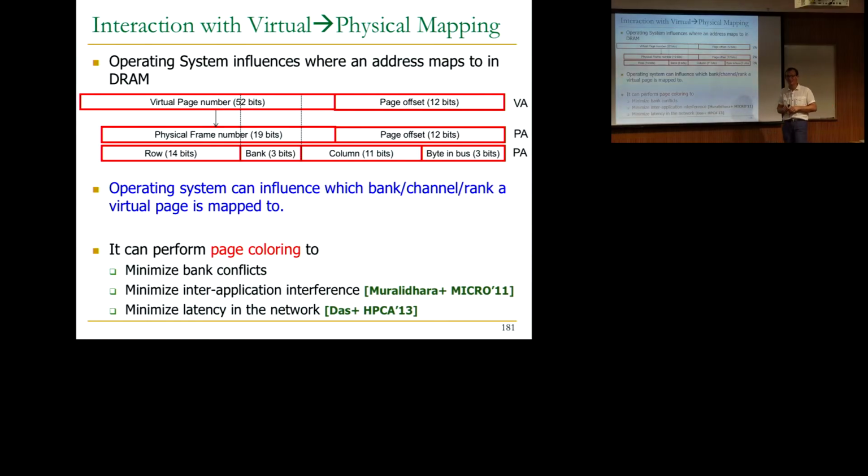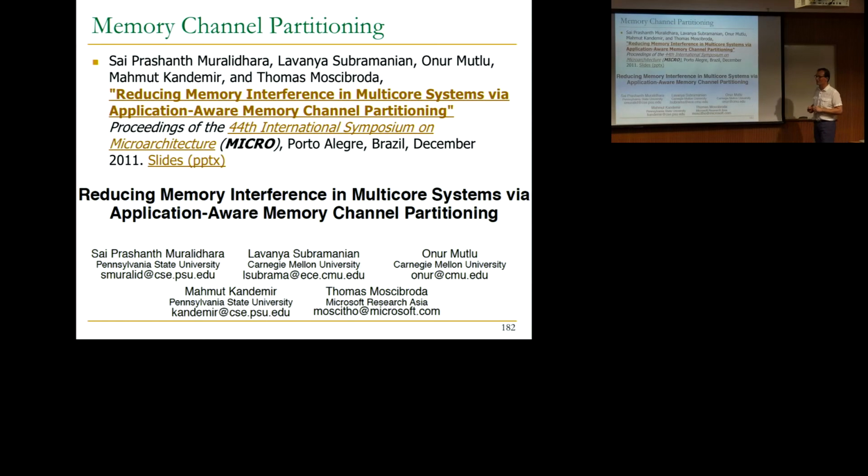That's limiting progress. Yeah, because I asked that because today you can buy some brand of a DIMM and you can just plug and play it, and that's all. You don't need to configure anything to install a DRAM. Well, there is this serial presence detect circuitry that I briefly showed inside the DIMM picture. That is the communication between the DIMM and the controller. Whenever you install the DIMM, the controller reads that and figures out what kind of a DIMM, what kind of latencies. Is it compatible? All of that. So any DIMM won't work with any slot, of course, right? Yeah. There are different DIMMs. Okay, but we're going to get back to the controller. That's the next topic, actually, very soon.